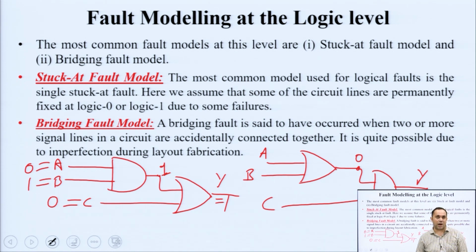So, what I am doing? I am designing a model. I am giving you a test case, a test structure. So, you apply logic 0 at A, you apply logic 1 at B, you apply logic 0 at C. So, 0 1 0 is a test case. This test case helps me to isolate that this line here is stuck at 1, okay?